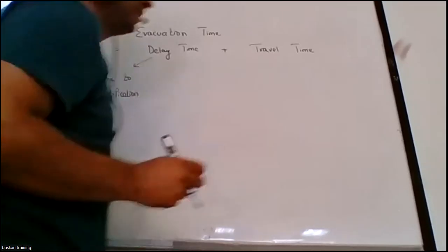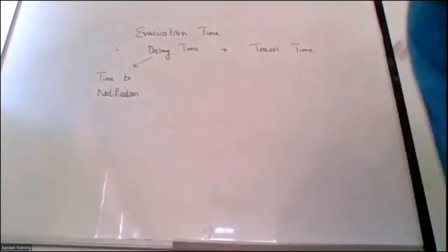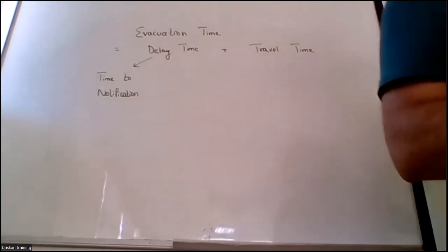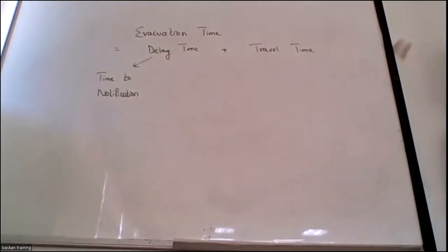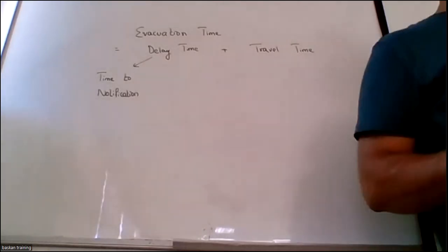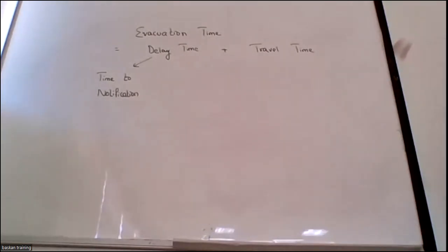In the first lecture, we discussed one thing. Whenever we are going to select among all the fire protection devices, detection plays a very important role. Why? An appropriate detection, meaning a detector with a good response, will give a timely notification. A timely notification means a timely evacuation. What's the use of your detector if it's giving the alarm with a 10 minutes delay? At that time, it will be difficult for your occupants to evacuate, right?